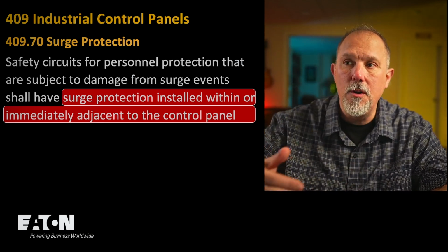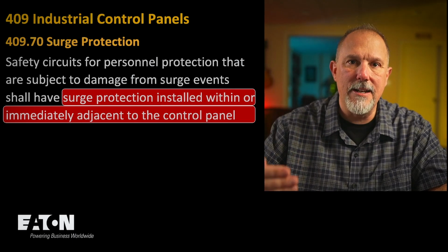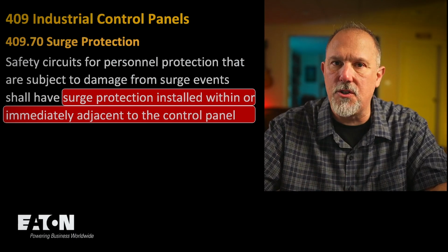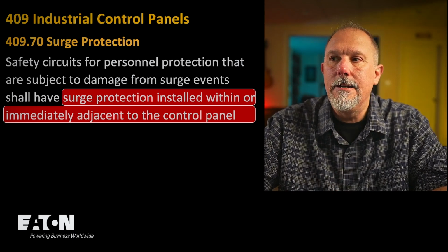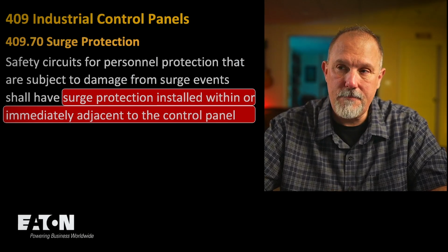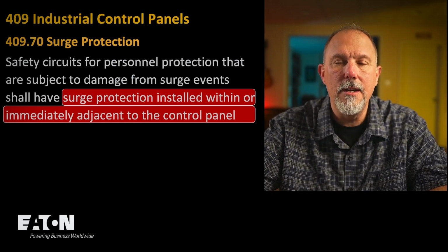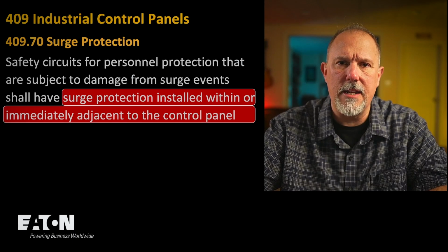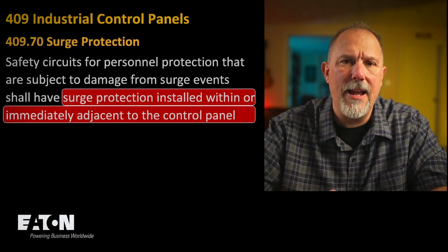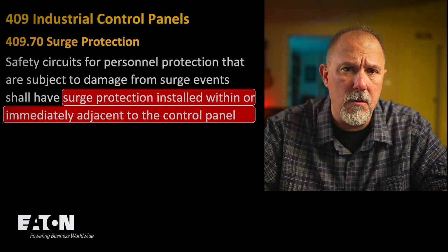Now, there's no performance criteria in here that says the lead length has to be a certain length. We do have requirements that tell you as short as possible. But to get to what an actual lead length maximum could be or should be is a complex scenario. So following manufacturer's rules and understanding surge, getting it as close as possible to the equipment and the components that you're trying to provide protection for is most critical.